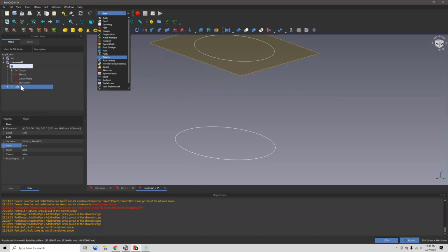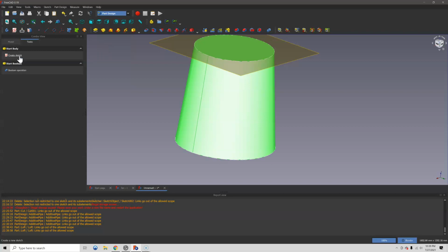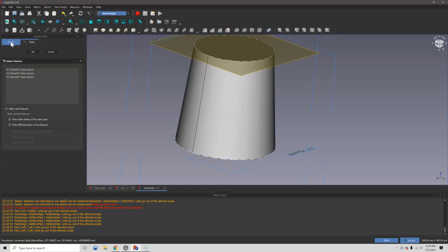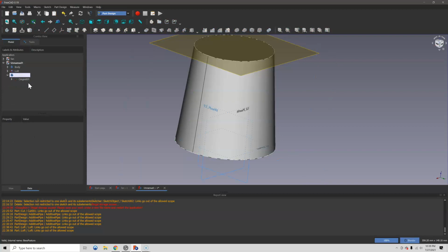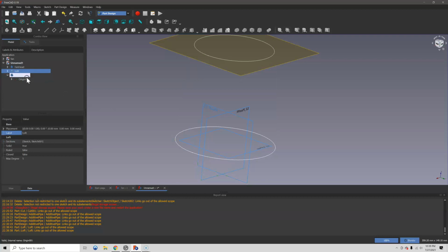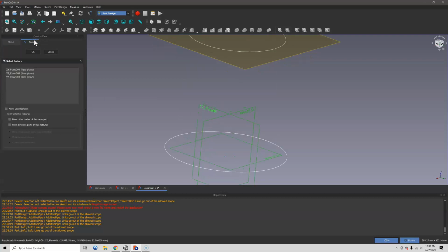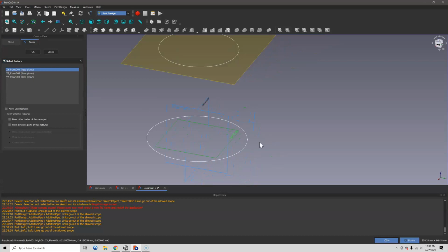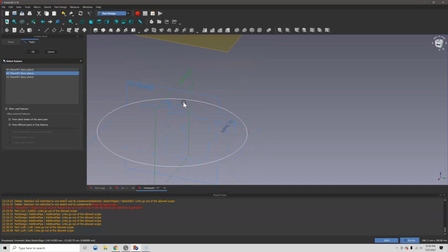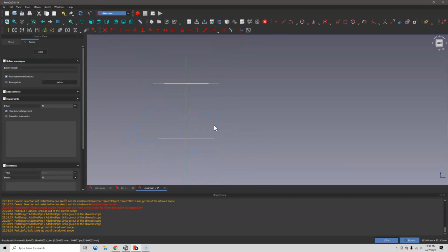Now we're gonna create the blades for the fan. So let's go to Part Design, create a new part, and create a new sketch. We don't want to reference the other sketch. Let's call this fan blade. Anyways, now we have a sketch. Instead of the XY plane, which is flat, we want to select the XZ plane because we want it to extrude to the side.